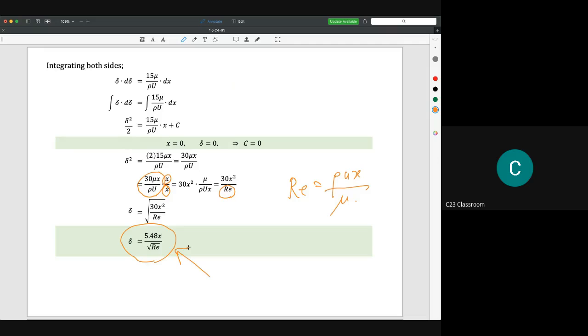That's why in fluid mechanics, a lot of equations use the Reynolds number. It is okay for you to show this one, and if you substitute values, you will get the right value of delta. But this is the best equation for delta, in terms of the Reynolds number, because in all textbooks they show the final answer for delta in square root or Reynolds number by the power of something, depending on the velocity profile.